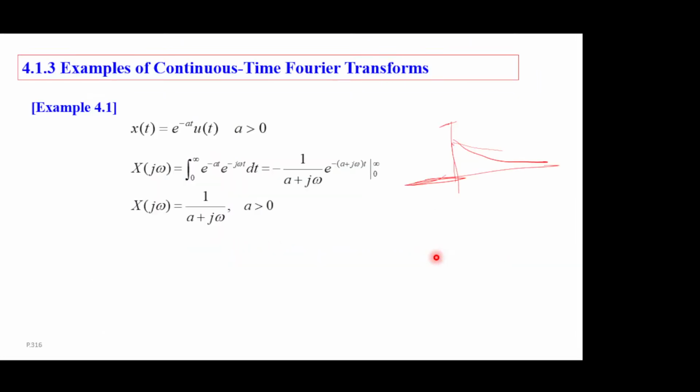And there's the maximum and the minimum. Well, there's basically one maximum, and it's a straight line, but let's say it's like one minimum here. And so it's like one maximum and one minimum. And for discontinuity, there is one discontinuity here, and that's okay. So this is a pretty nice function. You should have a Fourier transform. And indeed, we can calculate this big X of j omega, and we just do brute force integration. It will be this integration from minus infinity to plus infinity, your function times e to the minus j omega t.